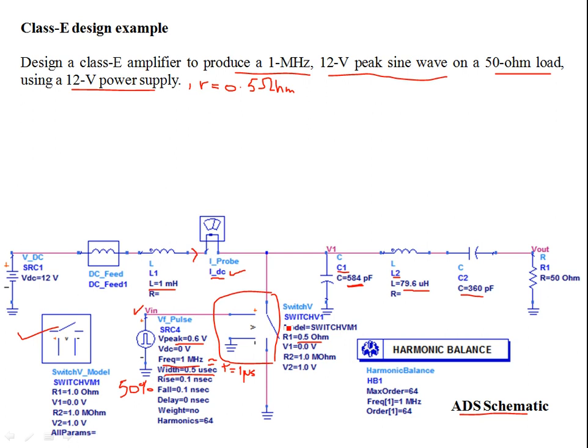So let's look at this node voltage Vn first, which is controlling the switching operation. It's a voltage controlled switch. It switches at 50% duty cycle, and then it effectively shorts once the switch is closed. It shorts V1, so V1 is 0. When it is open, you have rounded pulses. So what we are going to have is a current like this over here.